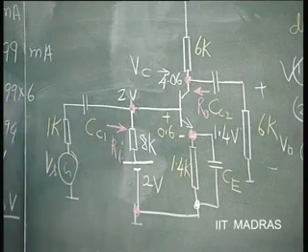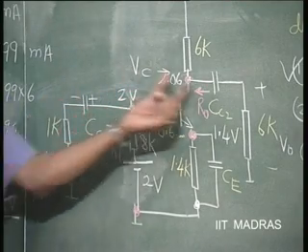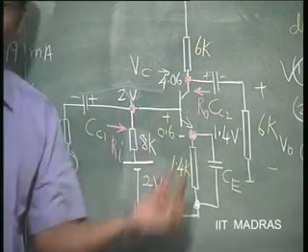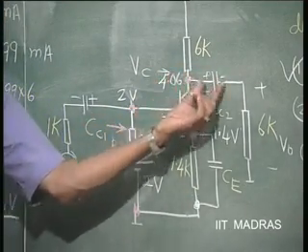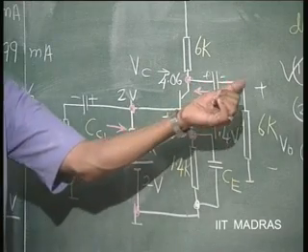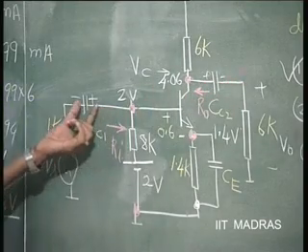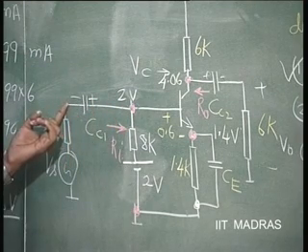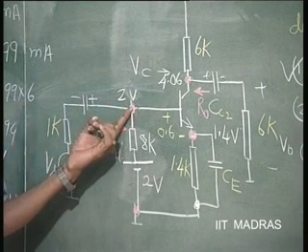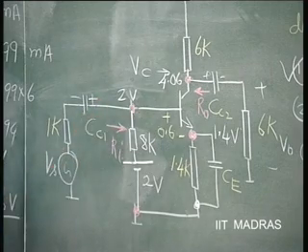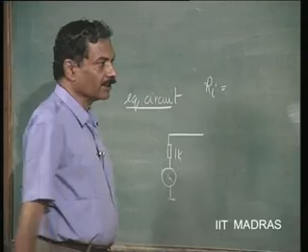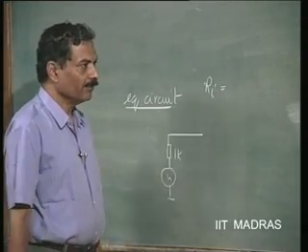How does it happen? Because the capacitor here gets charged to 2 volts. This capacitor gets charged to 4.06 volts. So, that will automatically get charged to the DC voltage, and therefore you get only the AC here. Similarly, this is automatically charged to this 2 volts. So, the signal voltage here is going to appear here over and above the 2 volts. So, we have 2 volts, capacitor is a short circuit. Again, compared with what?